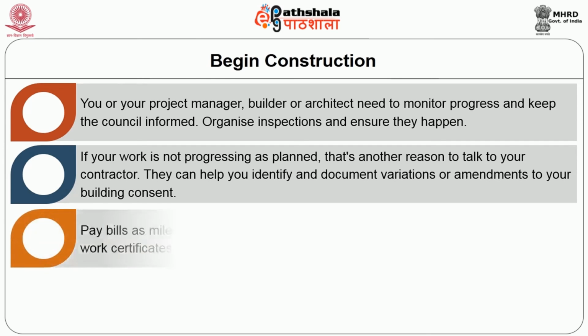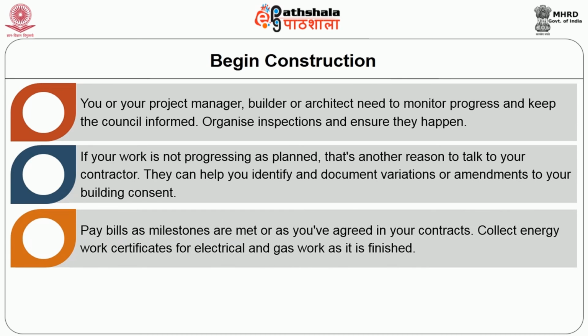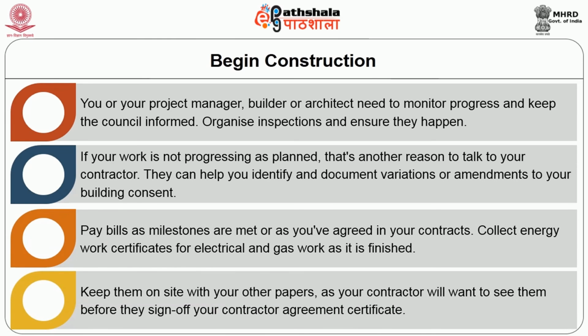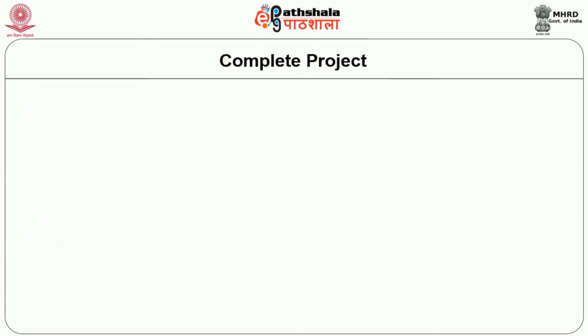Pay bills as milestones are met or as you have agreed in your contracts. Collect energy work certificates for electrical and gas work as it is finished. Keep them on the site with other papers as your contractor will want to see them before they sign off your contractor agreement certificate.